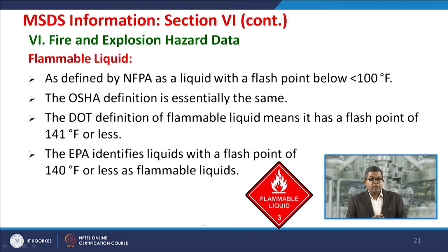Now, flammable liquid, what kind of definition does it have? Usually, as defined by NFPA, this is a liquid with a flash point below 100 degree Fahrenheit. I am repeating it again, that whenever you use this data, use it carefully, because 100 degree Fahrenheit is a bit different from 100 degrees Celsius. The OSHA definition is essentially the same and in close proximity to NFPA.